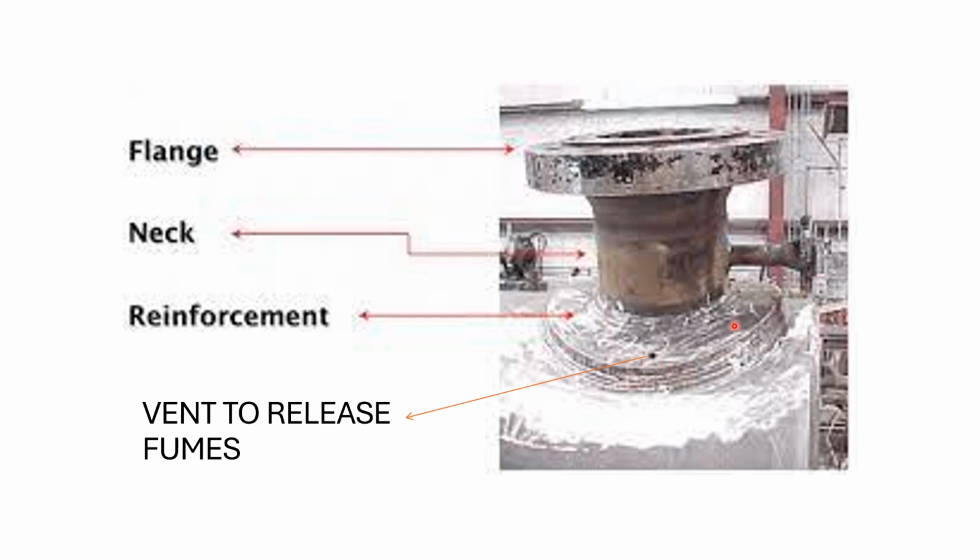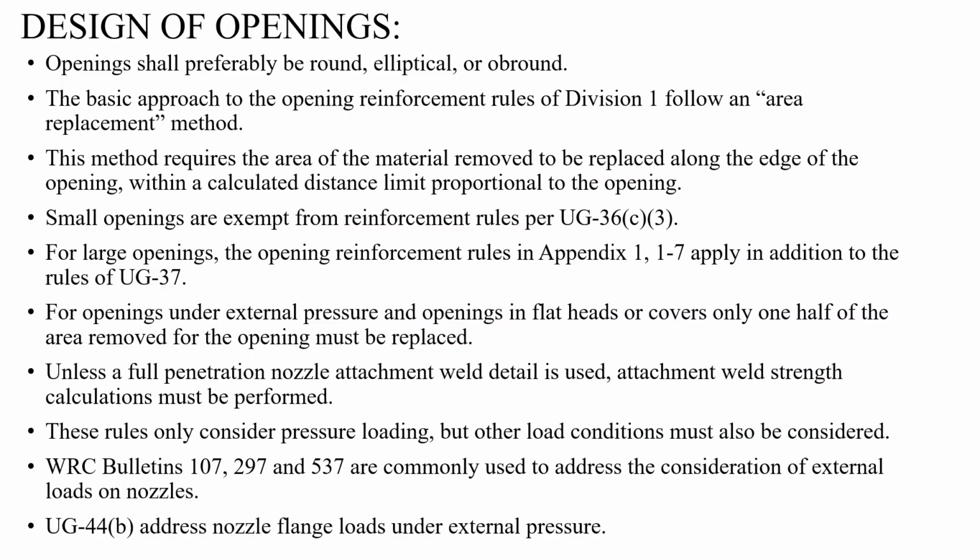pad. Okay, so now why is the reinforcement pad required? Reinforcement pads are not mandatory. It depends upon the size of the nozzle, how much size is required, and there is also one factor which is called the area replacement factor. We may see the area replacement in the next video, but we will see what the exemptions are to avoid the reinforcement pad.